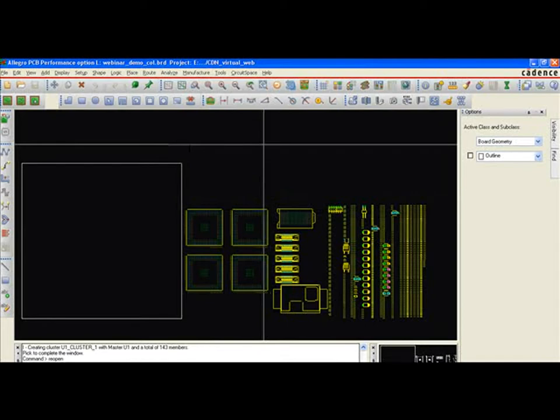One of the immediate benefits customers can utilize with CircuitSpace is its ability to help group components and provide initial placement of component groups. This helps give designers a head start as they begin to place their parts on the Allegro canvas. Instead of placing one device at a time, designers can place functional blocks of circuitry, effectively raising their level of design abstraction for placement. As you can see, we are currently inside the Allegro PCB Editor GUI. CircuitSpace operates directly within the Allegro PCB menu structure, so anytime you use CircuitSpace, you are automatically and natively updating the Allegro database as well.